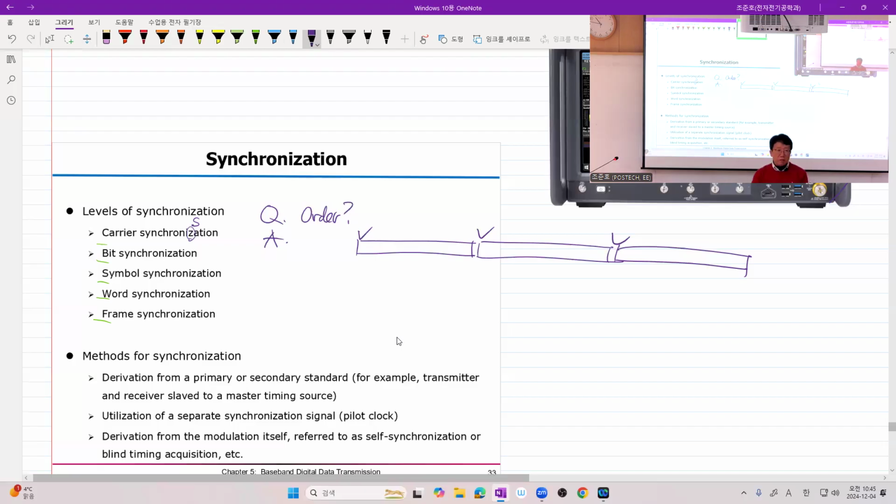So the received signal is very weak, which means the noise is very high, but you want to recover the carrier frequency first by squaring it. What happened? Noise is squared, which is very large, so it didn't work. So I modified the algorithm so that we recover the timing first, and then it worked very, very well.